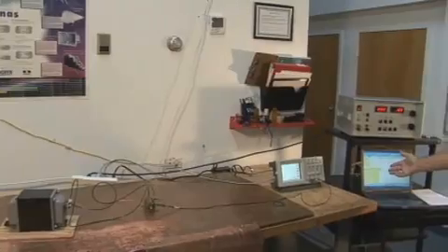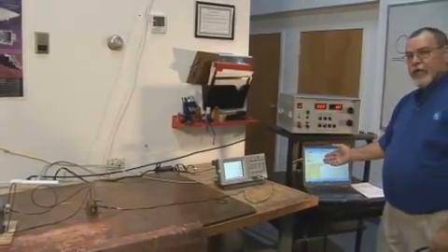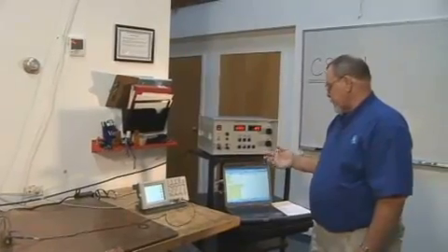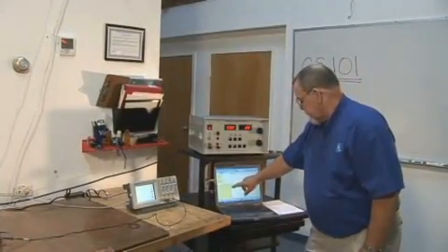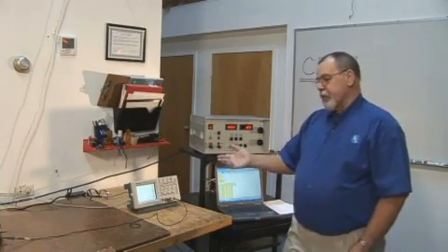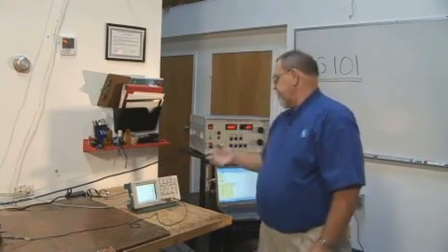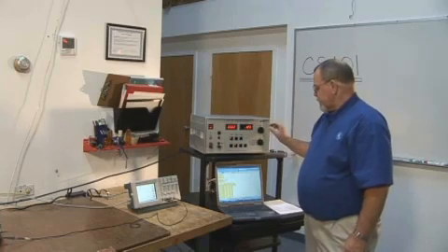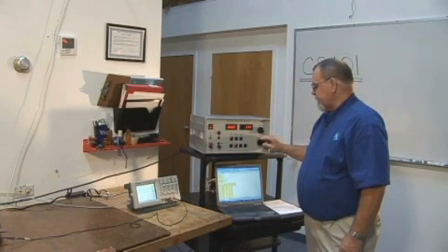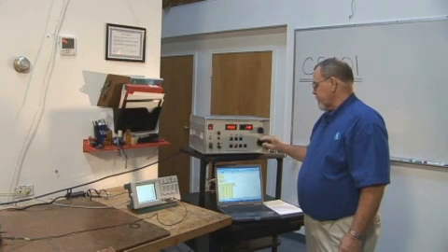We have predetermined what voltage we'll be applying for that 80 watt power dissipation. That's the requirement down at the lower frequencies. And the calculation shows that we need 6.32 volts to be applied at this frequency. Our start frequency is going to be 120 hertz, or twice the power line frequency. We have a 60 hertz test article that we're going to work with.